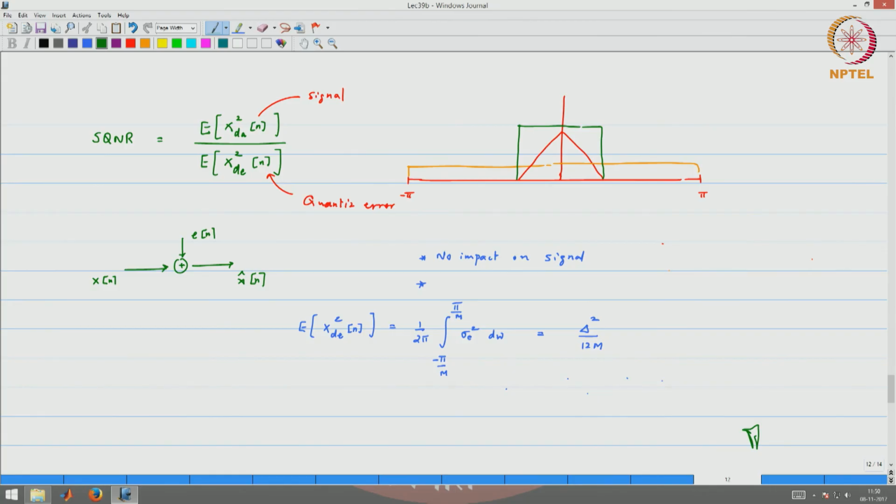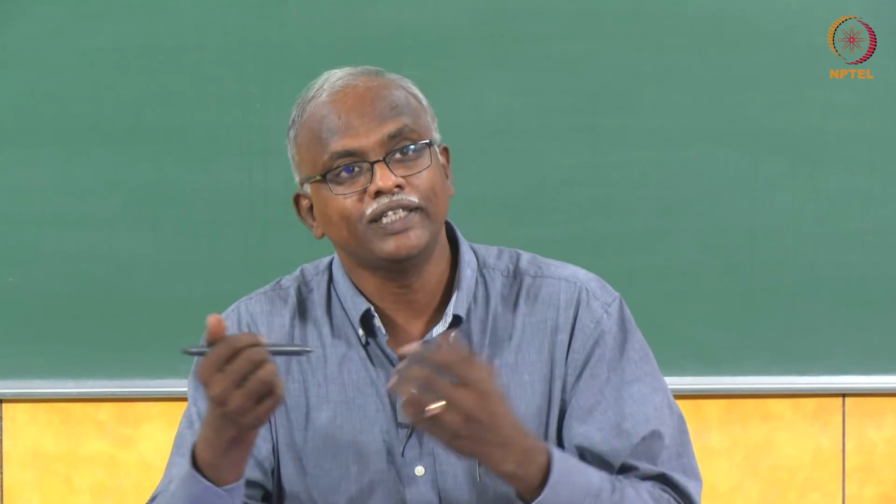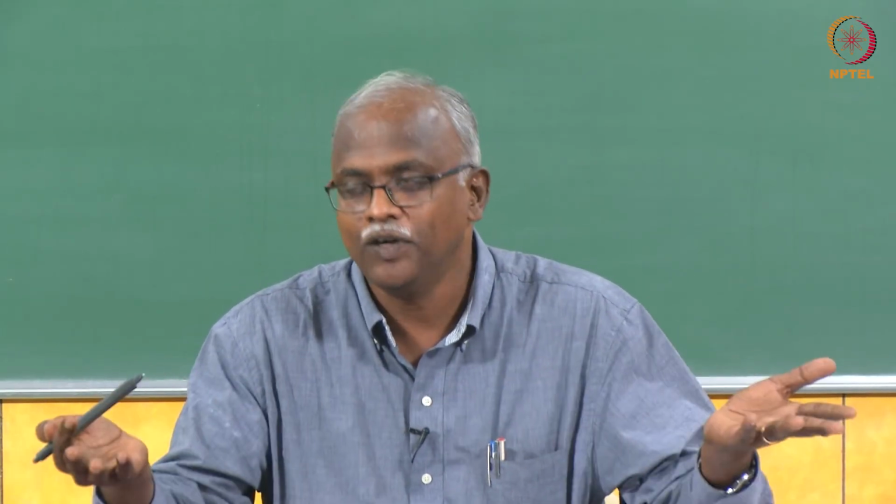Coloration of the noise depends on some kind of memory between adjacent samples. Only when you have memory can you introduce coloration. So if each of these samples is independent of the others, we cannot produce that. So, the question is, can you do something in terms of the coloration?